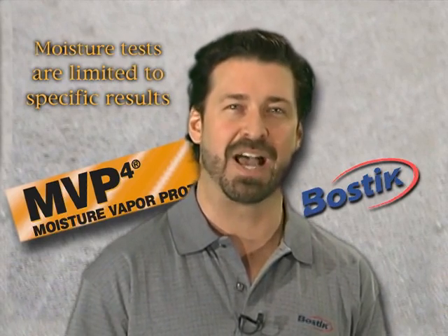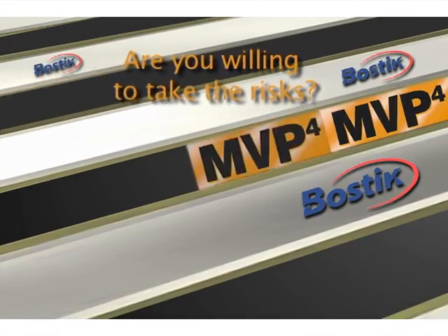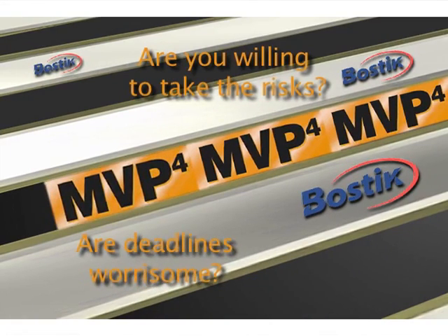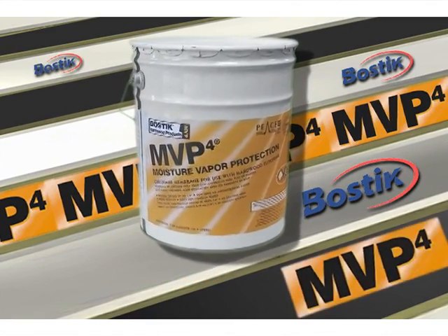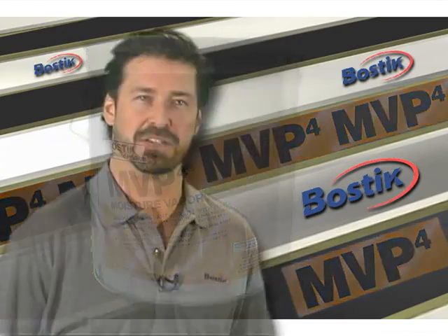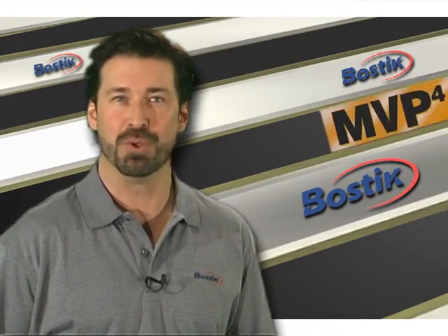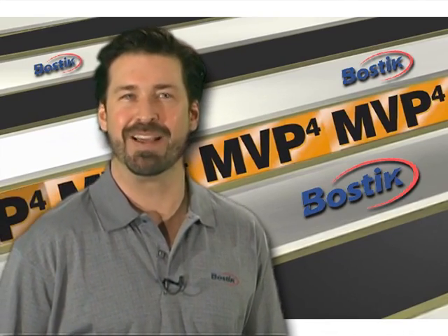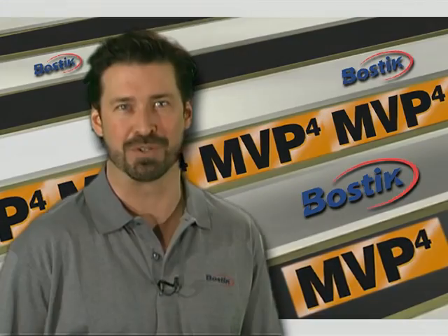And so, you must ask yourself, are you willing to take these risks with your wood floor installation? Do the increasing deadlines for faster and faster finished construction over green slabs have you worried? You can eliminate the what-if scenario and protect your wood flooring from future moisture damage by using Bostik's MVP4 system. Whether the moisture content of your substrate exceeds or is within the wood flooring manufacturer's recommendations, you can address current and possible future subfloor moisture concerns by applying a layer of MVP according to directions and allow the material to cure for a minimum of 12 hours.